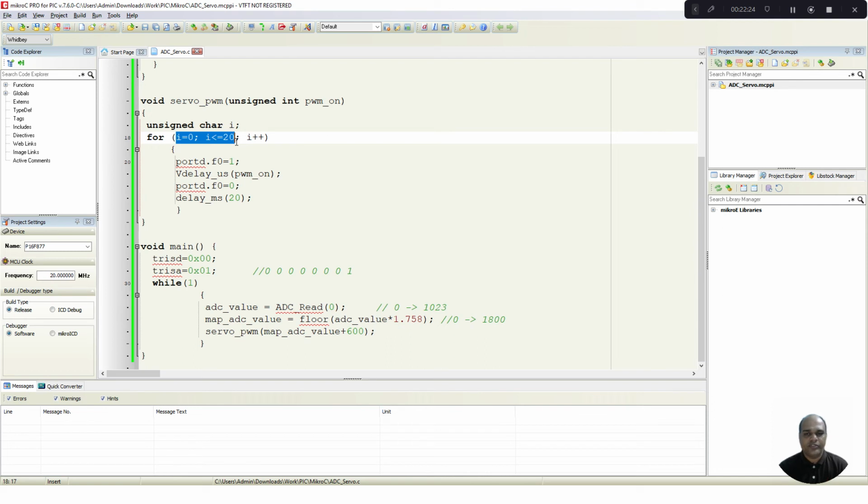to the desired position. So there is no harm in producing multiple pulses, because when it recognizes for the first time, the shaft will go to the desired position. When it recognizes for the second time, third time also, there will not be any change, because already the shaft is in the desired position. Thereby, precise positioning of the shaft can be achieved.